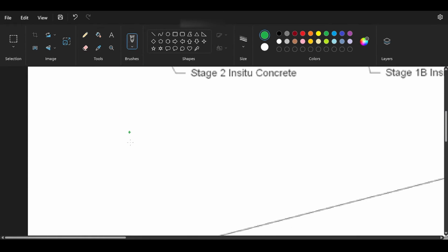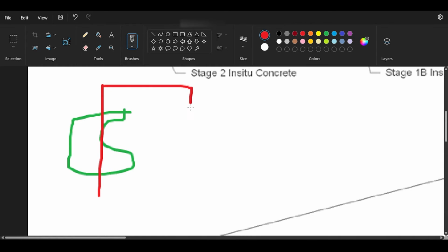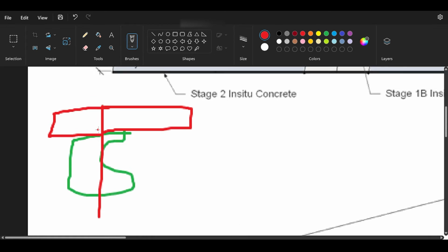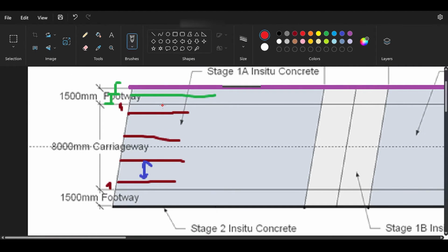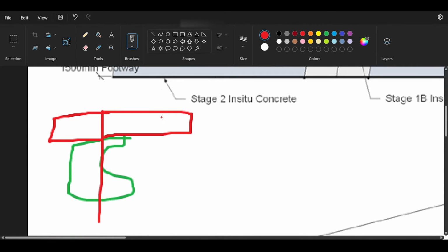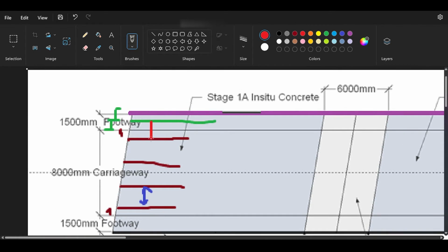So I'm thinking loud now. I'm thinking of making an edge beam like this. Now it looks like garbage. I know I'm not really the best of drawers. And let's say this is the centroid of the edge beam. I will have 1 meter on this side and half a meter on this side. That's my plan. Because like 1 meter everywhere. Why 1 meter? It's not because I like to do 1 meter. No, it's because I want to keep a center to center spacing of 2. And because this takes 1 meter, I have to have 1 meter here. Okay, so let's implement this.